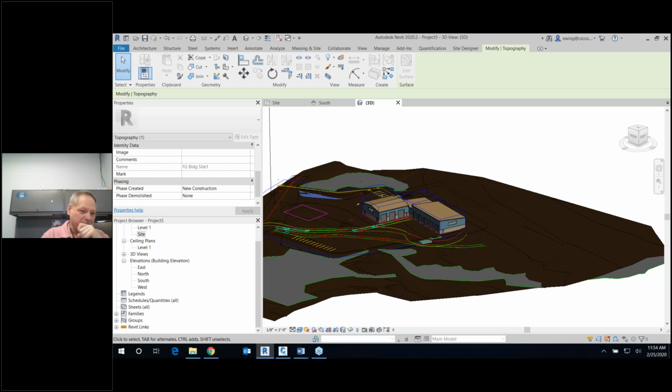It's going to put them at the correct northing and easting, but it doesn't know that northing and easting, so it's just going to be out in the middle of the field somewhere. I'm more comfortable unclipping and moving those to a known location. Again, it's not a detriment to the actual model. They're still going to drop in the same spot.